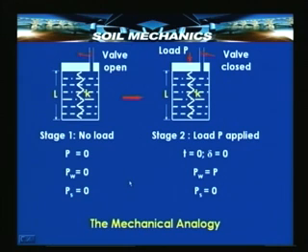Now comes the second stage, where we apply a load P. This simulates the construction of a structure. The moment a load P is applied, we start counting the time for the compression phenomenon. The compression phenomenon really gets initiated only after the load is applied. So, the moment the load is completely applied is the time t equal to 0, at which the compression phenomenon may be considered to have got initiated.